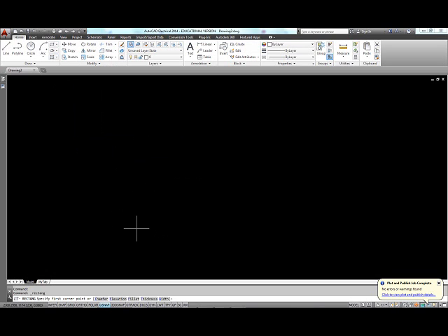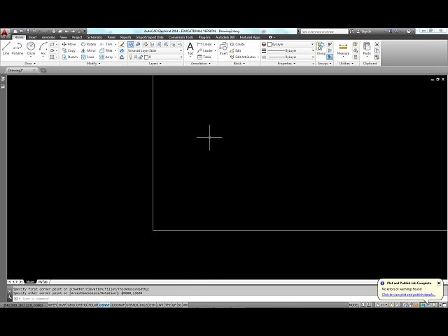I could click anywhere, or I could go 0, 0. So I'm going to click here. I'm going to say at 9080, comma 13620. Watch what's happening here at the command window. These are the coordinates of the opposite rectangle. Once I finish that, it's enter. Then double click the wheel.